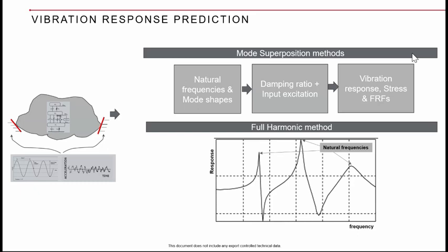But when you come to actual problems, you may have to adequately capture the mass distribution and the stiffness distribution of the system. So you need many degrees of freedom to properly represent it, which is not possible to handle with hand calculation methods. So therefore, what you will be ending up doing is FE analysis, which everybody does for vibration analysis.